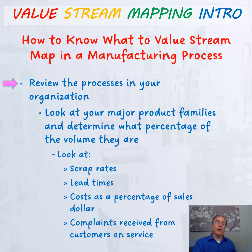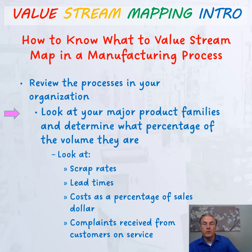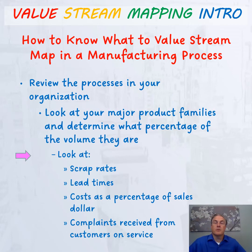So how do you know what to value stream map in a manufacturing process? You review the processes in your organization, right? So you look at your major product families, determine what percentage of the volume they are, and I'd focus on the major product families. But as you do this, you may want to look at scrap rates. You may have a particular product line where the scrap is really high. You may want to look at it in terms of first time yield, right? You may want to look at your lead times. If you've got a process where lead times are really, really high, that's a good candidate.